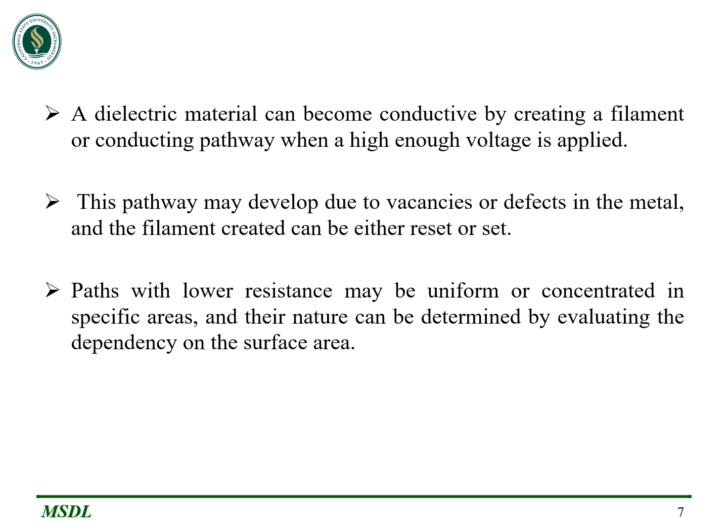A dielectric can be made to conduct through a filament or conduction path formed after application of a sufficiently high voltage. The conduction path can arise from vacancy or metal defect migration. Once the filament is formed, it may be reset or set. The low resistance path can be either homogeneous or localized. They can be distinguished by measuring the area dependency.